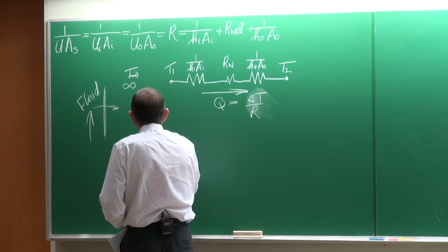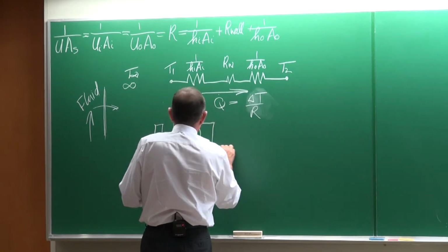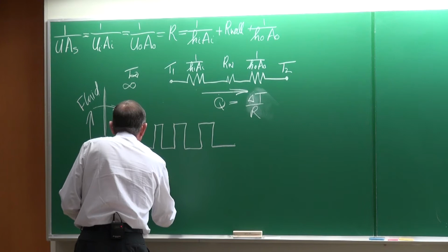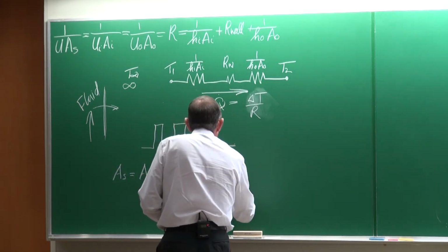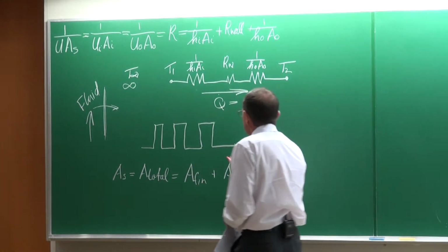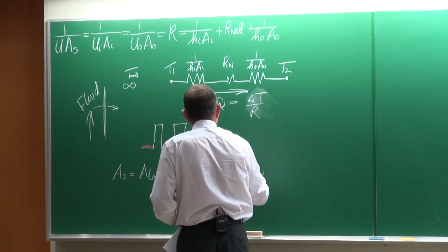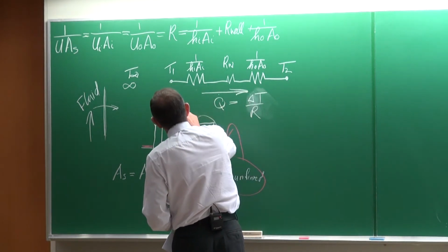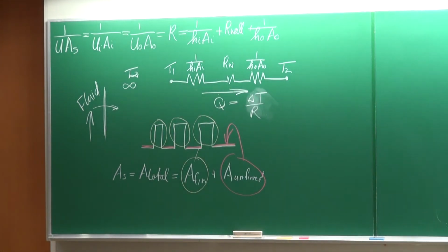And one way of improving the heat transfer is to make use of fins. I'm going to show it like that. And then we're going to say, well, this total surface area is going to be the total area of heat transfer, and that would consist of the area of the fins plus the area of the unfinned part. Okay, now the unfinned part would then be these areas there. So that would be the unfinned parts, and the finned parts would of course be those areas there of the fins. That part there. Okay, so it's very easy to calculate.